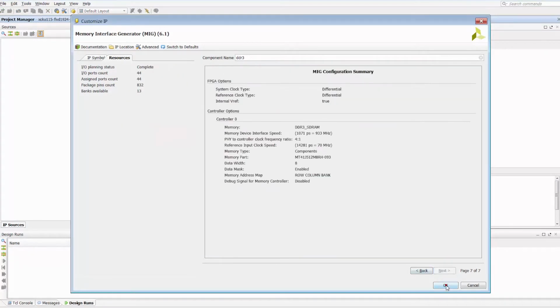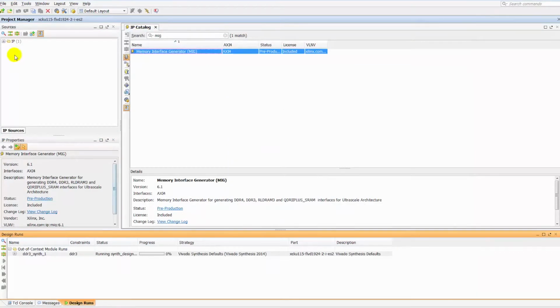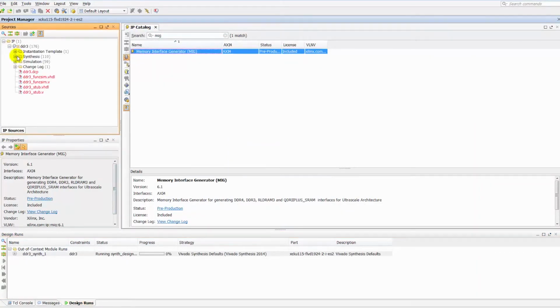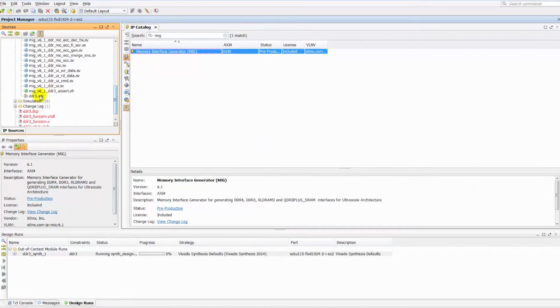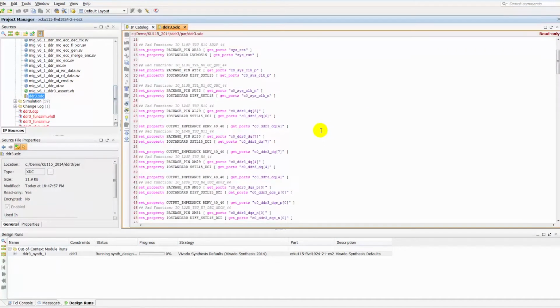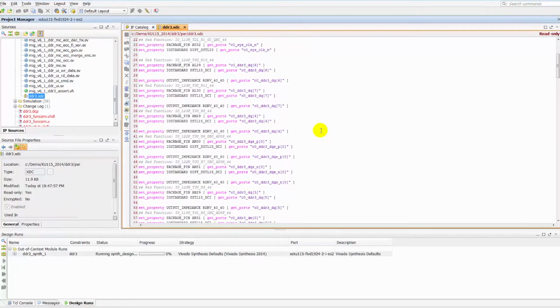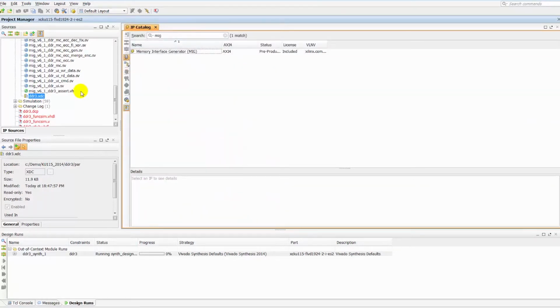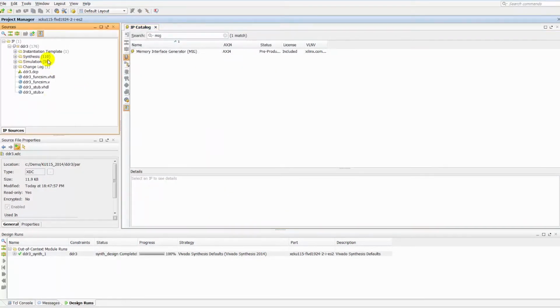When the output products for the IP were generated, an IP specific constraints file contains all the physical constraints, including the package pin lock constraints for the IP I/Os. This essentially locks the IP with this group of I/Os. Any modification to the I/Os or any retargeting of the IP required regeneration of the output products, which made seemingly simple printed circuit board pin swaps very cumbersome.